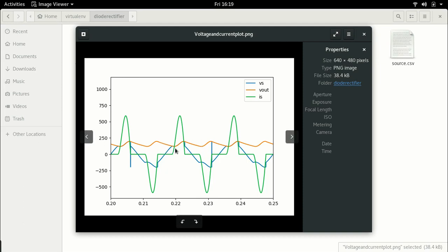And the large amount of ripple is mainly because of the large inductor at the AC source. Because when you have a large inductor, there is a huge drop across that inductor. And similarly, the source voltage drops so much because there is such a large drop across that inductor. So all we have to do is change the inductor and we are good to go. But this shows that the circuit is working, the simulation is working.